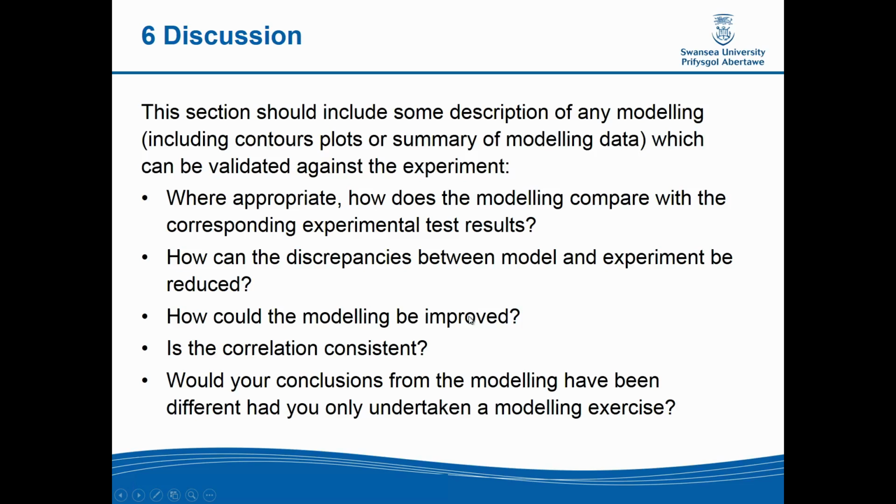How could the modelling be improved? Beware of mesh sensitivity, so refining your mesh doesn't always give you better results. Refining your mesh might do, but fluid dynamics is a very non-linear problem, and you might not be able to get better just by refining your results.